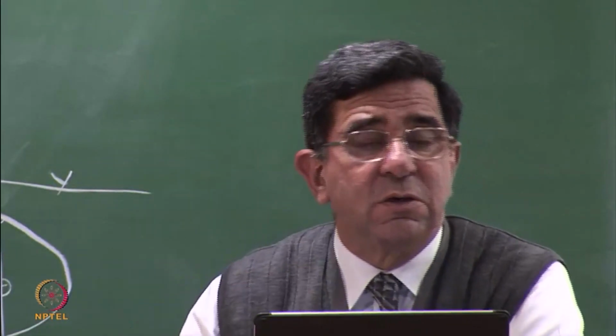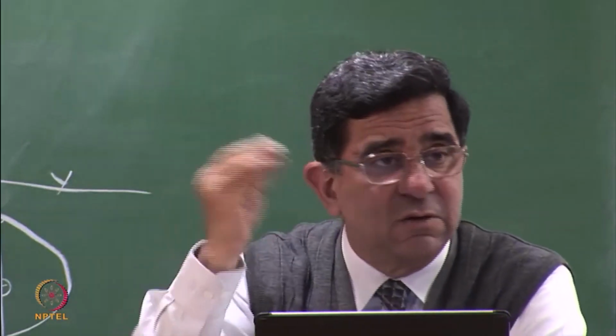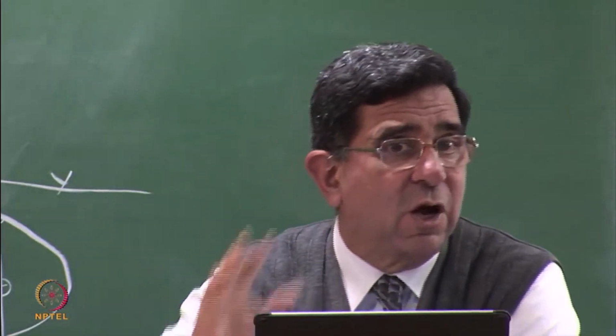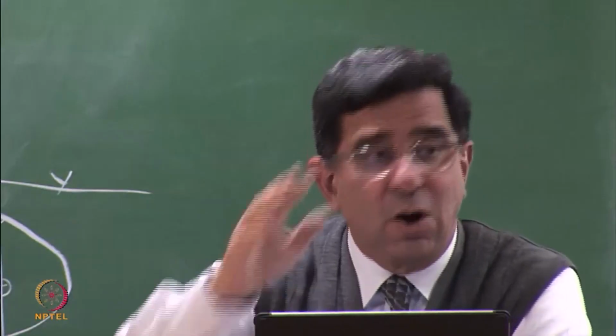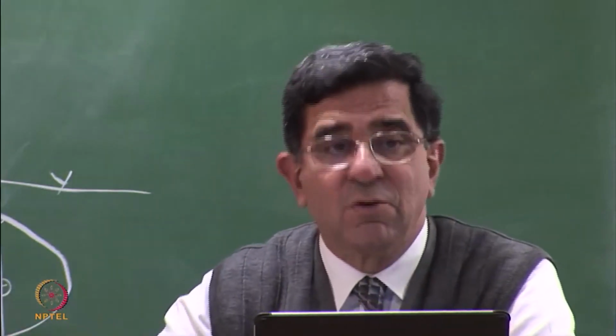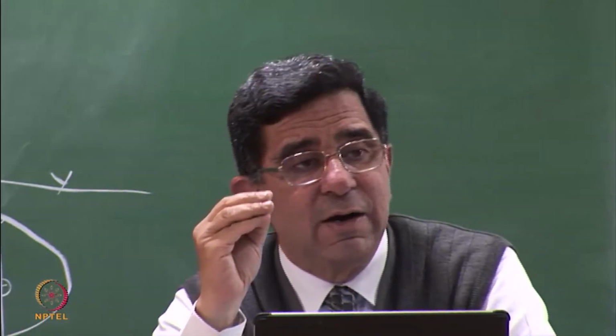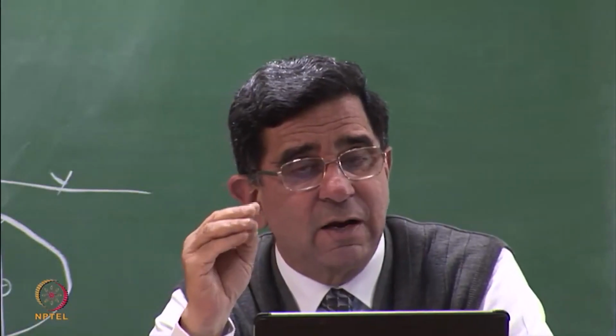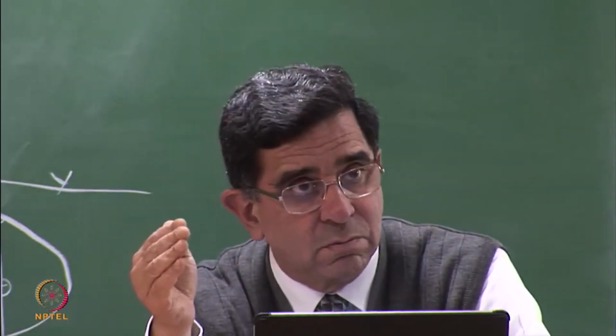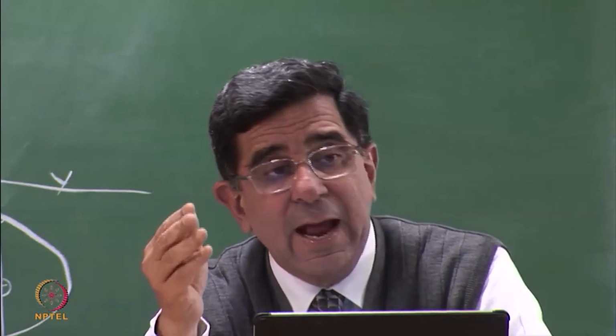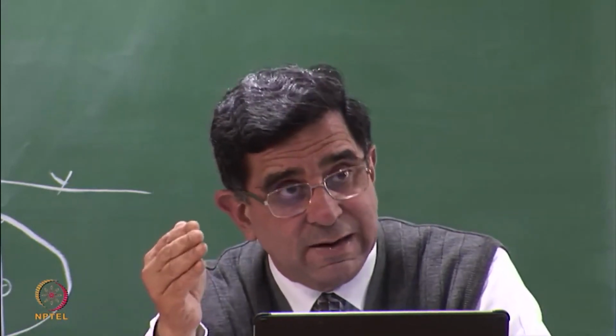Amongst those constituents, the reactive ones are not of interest to you. Why? Because the soil will attenuate them. The non-reactive will go through. So, you will really be looking at your contaminant of concern which is non-reactive because it will lead the plume, right? And therefore, you can detect it.